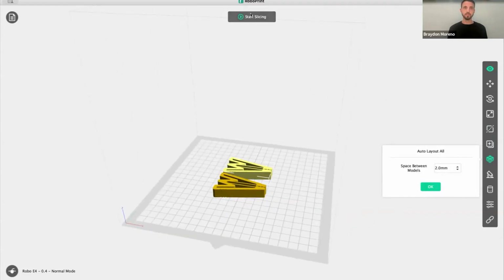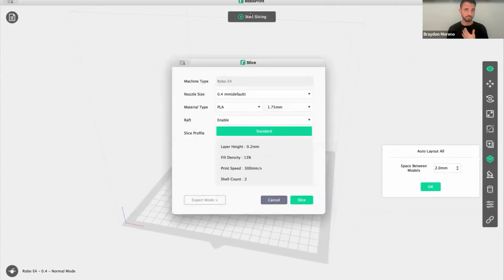When you go into slicing, I'm going to click this little start slicing. Now, once again, we've pre-built settings that are sort of best case scenario, or highest probability of the print that you place in the software having success. But I want to give you a couple of tips and tricks of things you can change. One of the things is, this raft, we always enable.